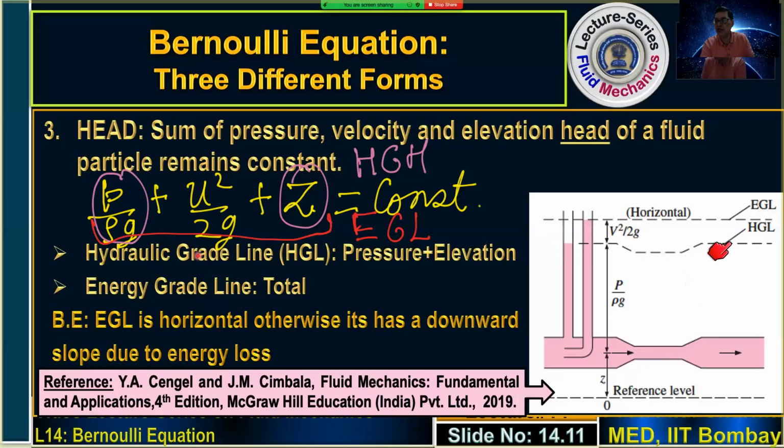Because here we are considering negligible frictional effects. So the pressure when it is flowing through a pipe is not reducing. So this way, for the flow in a pipe with a nozzle and a diffuser, taking a piezometer and pitot tube, basically we are considering the pressure variation due to change in the pressure and velocity variation due to the change in the cross-sectional area. We are not considering the pressure variation due to the frictional effects.